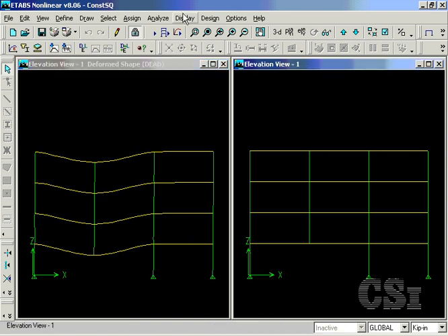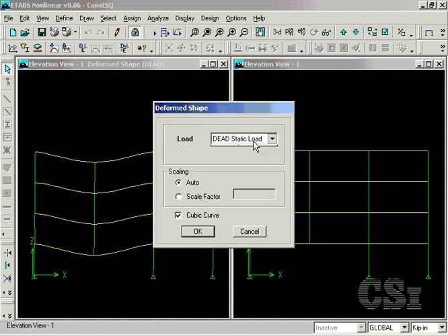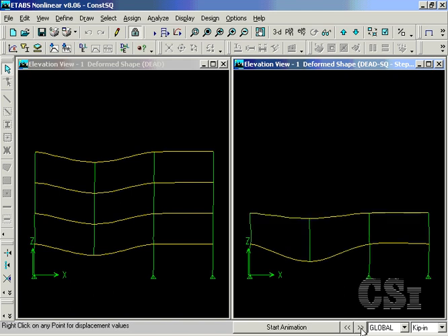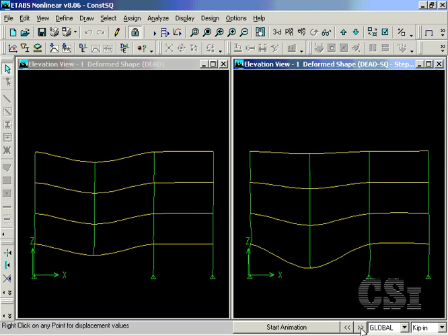In the right window, we will display the deformed shape from the sequential loading to see the effect that this loading approach has on the building. We set the scale factor to 200 to match that on the left. Starting with step 0, the first floor undeformed, we can toggle up the construction stages. Note how the displacement at the transfer girder location grows significantly larger than that of the model where no sequential behavior is accounted for.